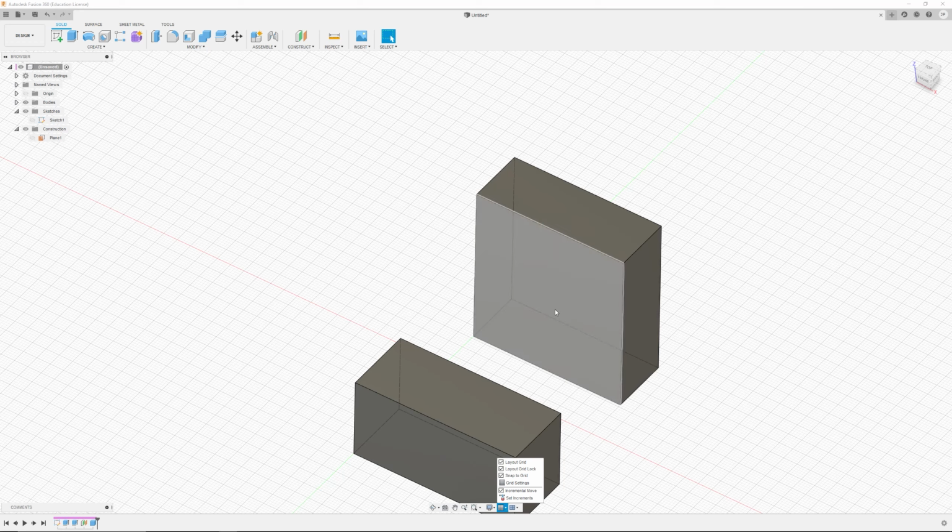Currently we're showing our layout grid, and we want our layout grid lock to stay active, and we want snap to grid always. The reason you want snap to grid is just as you are dragging lines to points, it makes it a lot easier to create stuff if you're not just arbitrarily placing lines willy-nilly. So leave snap to grid on.